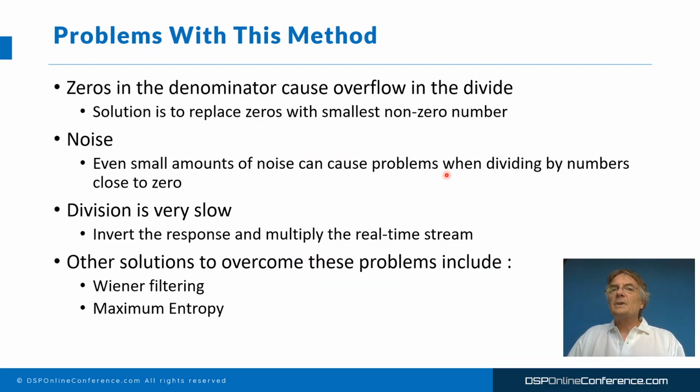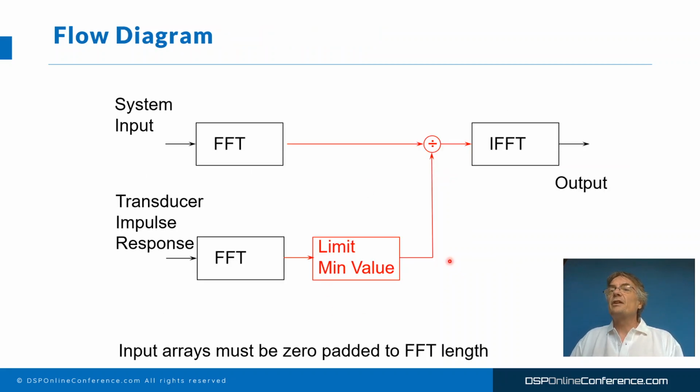But you can't always do that, so there are other algorithms, Wiener filtering, maximum entropy methods, that can be used to overcome some of these problems. But for basic transducer frequency response linearization, this is a very, very handy process to be able to use.